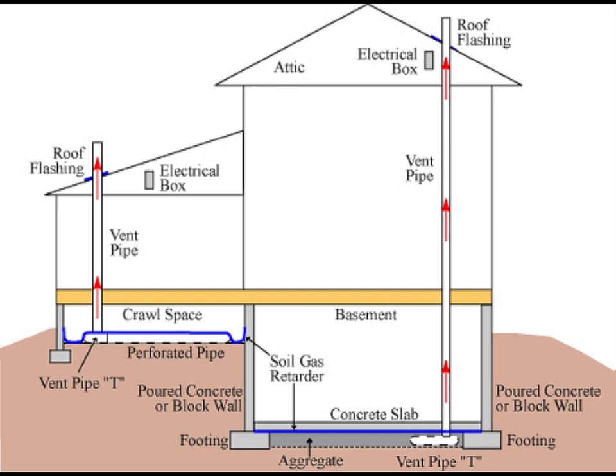A vent pipe. Use a 3-inch or 4-inch solid PVC Schedule 40 pipe, like the ones commonly used for plumbing. Run the pipe vertically from the gravel layer, stubbed up when the slab is poured, through the house's conditioned space and through the roof to safely vent radon and other soil gases outside above the house. Although serving a different purpose, this vent pipe is similar to the septic drain waste vents. This pipe should be labeled Radon System.